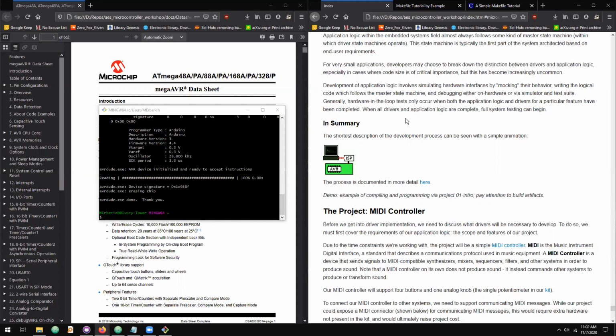So you'll cover every edge case of what the driver can do. And from there, you'll either use the programmer debugger to inspect what's going on at the programming interface for each of your hardware devices, or just run a pre-configured test and check the outputs of the device to make sure they're working. But as soon as you get to the application logic being complete, there are additional tests that you can run to validate performance.